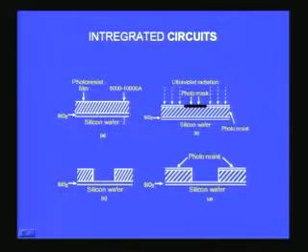1 angstrom is 10 to the power of minus 8 centimeter or 10 to the power of minus 10 meter, and so you have on the silicon wafer a small layer of silicon dioxide, which is called an insulating layer, and over which you put a photoresist film, and then you put a mask on top where you want no device, and where you want the device you don't put any mask, and you expose it to ultraviolet radiation.